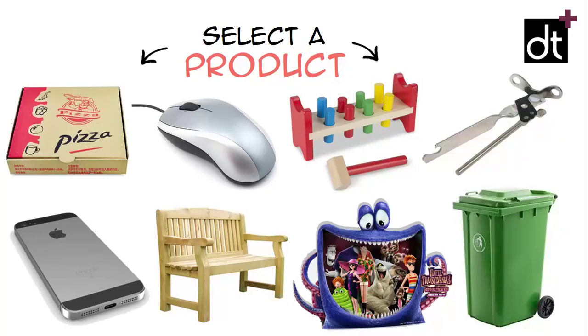The answer would be corrugated card is thick. It has got a hollow core within it, which allows it to insulate and to keep the pizza hot. It's also thick, which allows it to be strong and keep its shape whilst in transit. It's been offset lithographically printed because that is a cheap way to mass produce products with only very few colours. So that is what I would suggest for you to really push your understanding of materials, manufacturing techniques, and associated design issues.